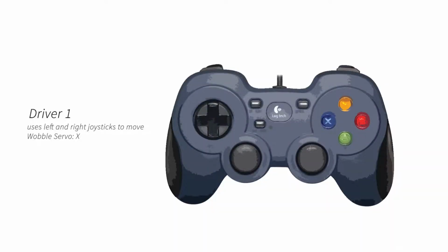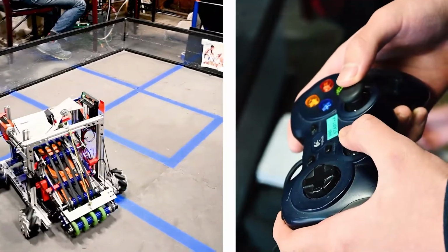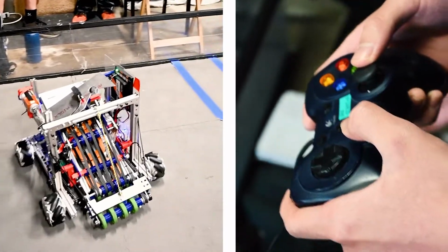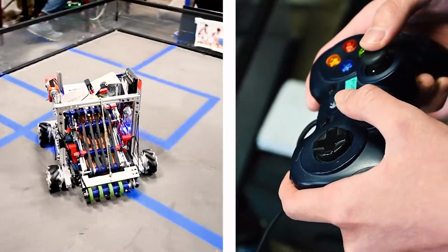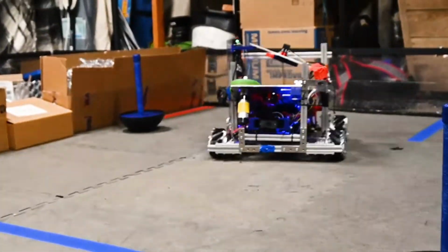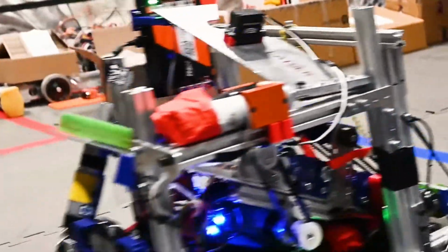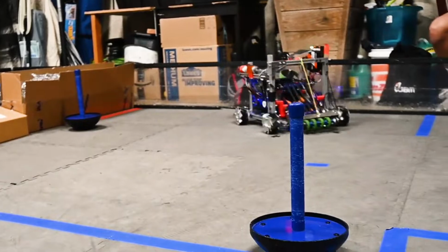For driver 1, we have programmed the controllers so that there are different buttons allowing for the driver to move at 50% power, 75% power, or 100% of the power, allowing for the robot to make fine adjustments or move fast across the field. We also incorporated PIDs into our controller because when the driver moves the joystick in a direction relatively straight to forwards, backwards, right, or left, our code changes it so that the drivetrain moves in a completely straight direction for super straight paths.